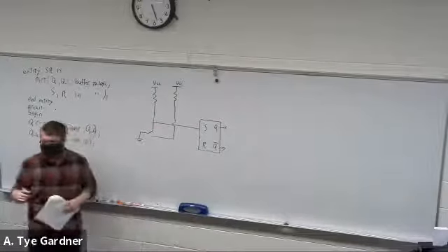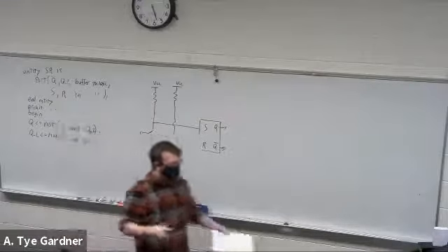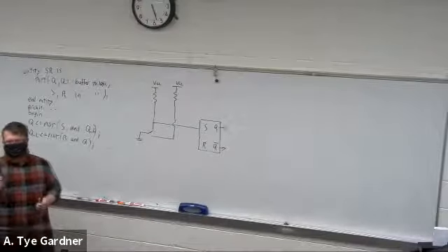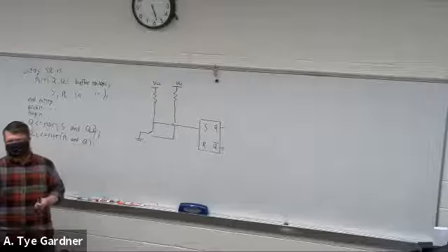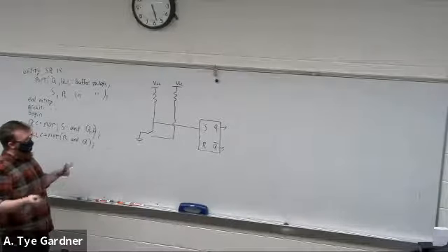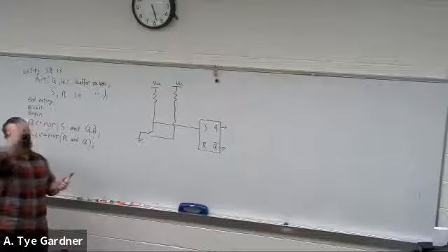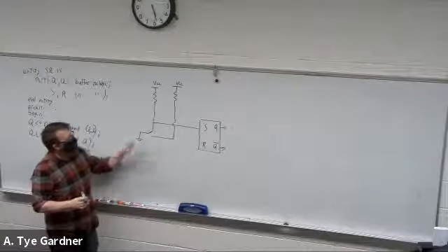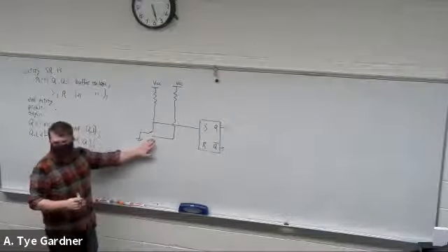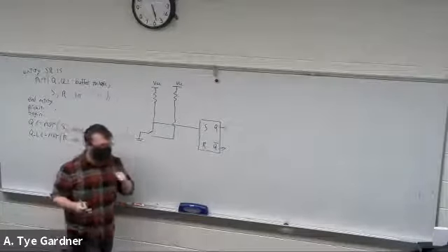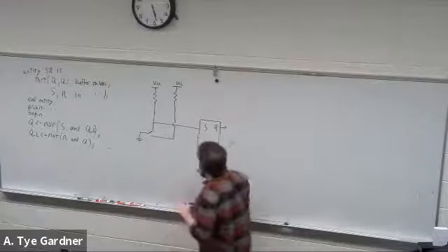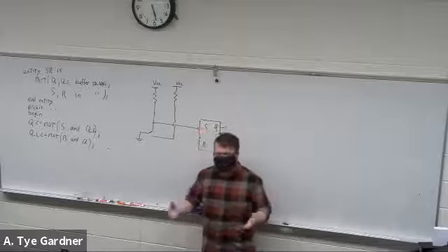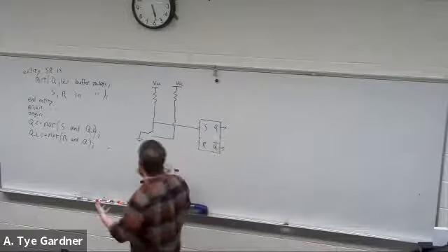A little bit different. So what we've been dealing with before is what we call single pole, single throw, meaning there's one switch and it goes from one thing or not, right? This is a single pole, double throw, so there's one switch and it's either here or here. There's 2 positions. So now what you'll see is both of these I can connect to ground. Their default state is 1. Their default state is power, which is going to be a problem the way I currently drew this with the pull-ups. So I need to make them active low because their default situation is going to be high.